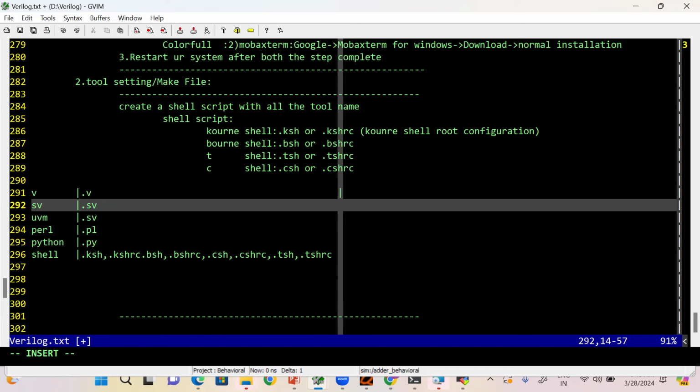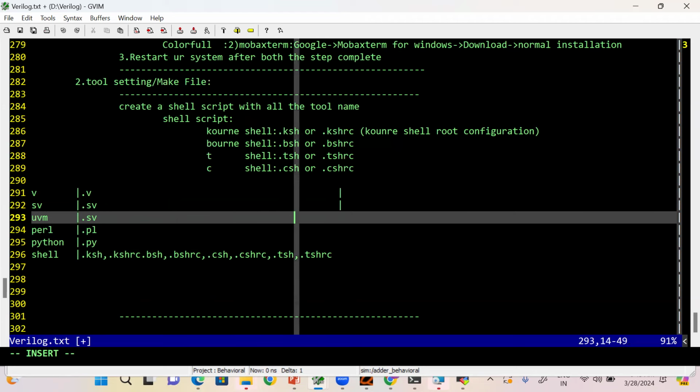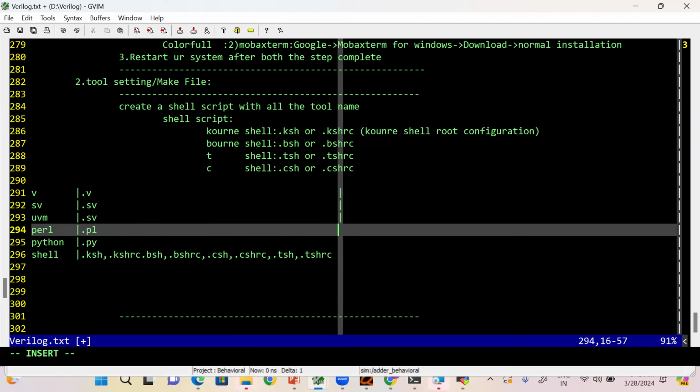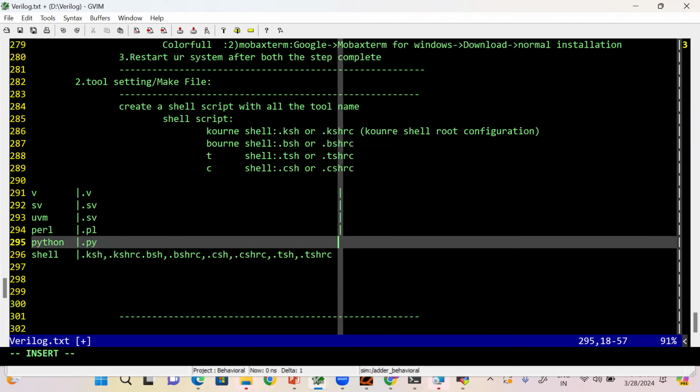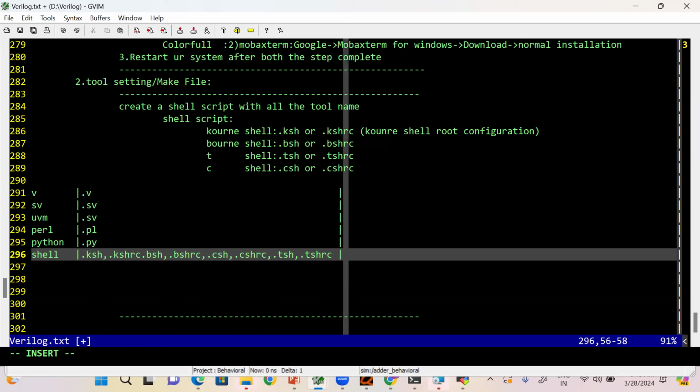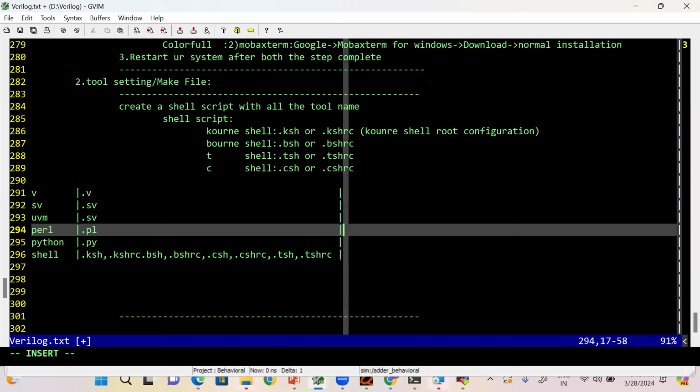One more table is there for you. Now first, Verilog code, you know how to run it. How will you run a Verilog code? I explained those steps yesterday. First you go for project, then compile, then simulate, then add wave, then run. These are the steps. If you do them, then only your Verilog file will run.